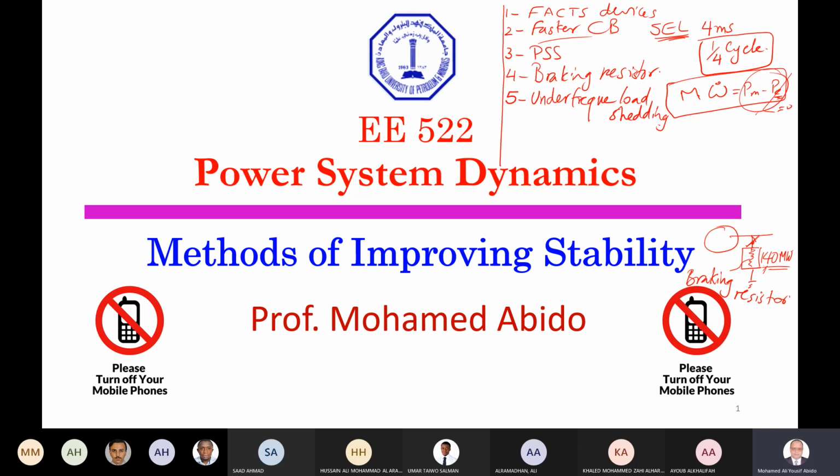If it is below, then you switch it off. And it goes on, off, and so on. And of course, you have a control scenario here. So under frequency load shedding could also be one of the solutions if we experience a decrease in the frequency.